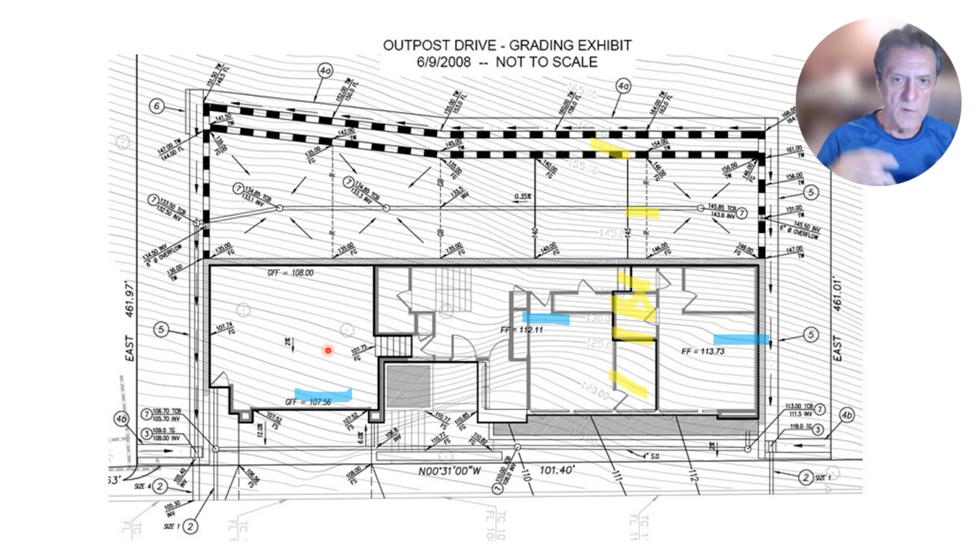So when you're doing the investigation with your exploration equipment, you want to make sure you drill down to the elevation that's going to be at the finish grade and deeper. Go deeper than the pavement elevation, because you also have to judge soil conditions for utilities which might be installed at a deeper depth than the parking lot grade itself, for example.